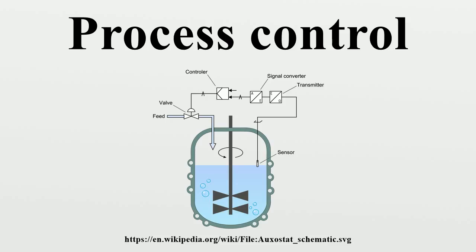For example, if an adjustable valve were used to hold level in a tank, the logical statements would compare the equivalent pressure at depth set point to the pressure reading of a sensor below the normal low liquid level and determine whether more or less valve opening was necessary to keep the level constant. A PLC output would then calculate an incremental amount of change in the valve position. Larger, more complex systems can be controlled by a distributed control system or SCADA system.